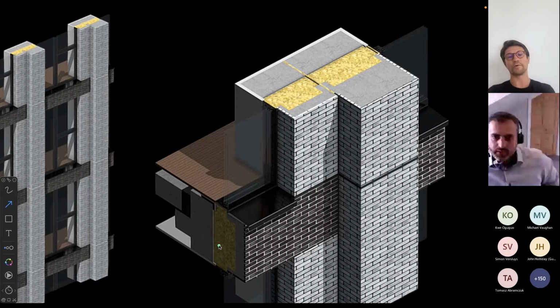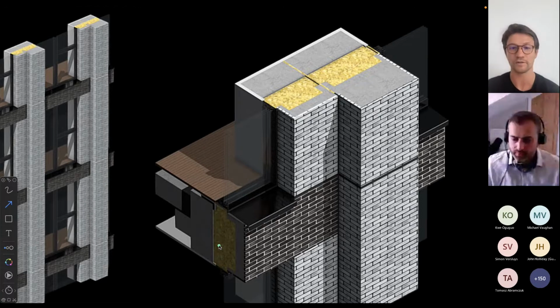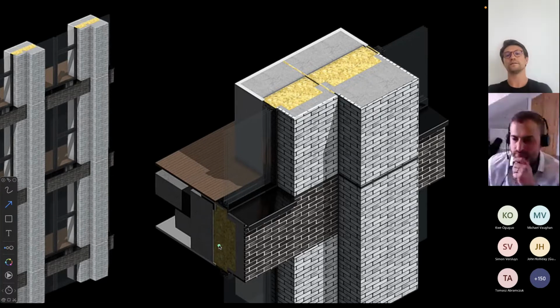However, that comes at the price of not having flexibility of design. Whatever the contractor can provide, it will be a very repetitive building. It would be a panel building. There will be lots of restrictions, and it will look panelized, and you have to be very creative with creating recesses and changing the pattern of the brick to conceal the panelized nature of the building.